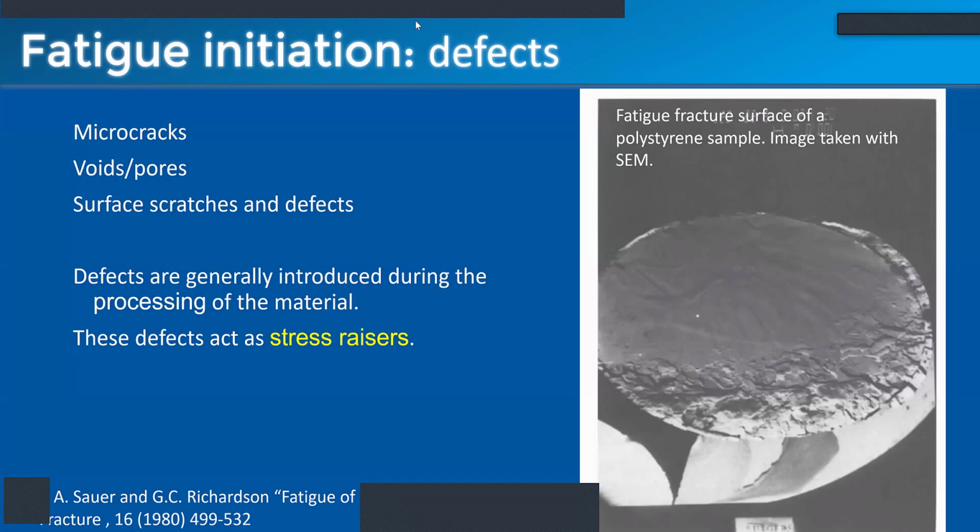Because we can tune the properties of the materials, we can make them match those of the native tissue in the body. Metals and ceramics generally have a higher strength than most of the materials in the body, and that can cause problems like stress shielding. But polymers are softer. Our bodies are softer. And so it's almost easier to match the mechanical properties of polymers to our native body tissues rather than metal or ceramic.